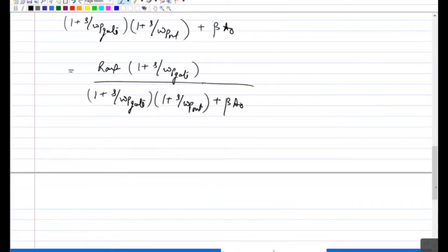Beta naught multiplied by square root 3, because beta naught is your UGB and you want to keep your second pole, the non-dominant pole, square root 3 times higher. So beta naught square root 3 will be your separation between the two. Okay, so can I say that when I'm interested only within UGB, which one will be dominant?